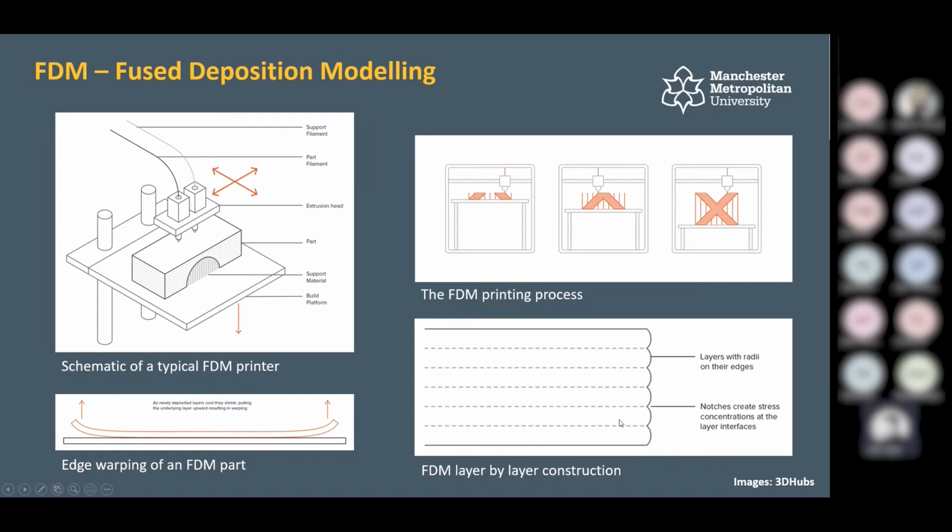Again, it's going to be printing in layers. So the actual surface finish of this is going to be kind of bumpy, like this outer edge here. This is a good thing and a bad thing. I would say it's mostly a bad thing, if I'm honest, because it means it's going to be a lot of post-processing required if you wanted to fix these things.